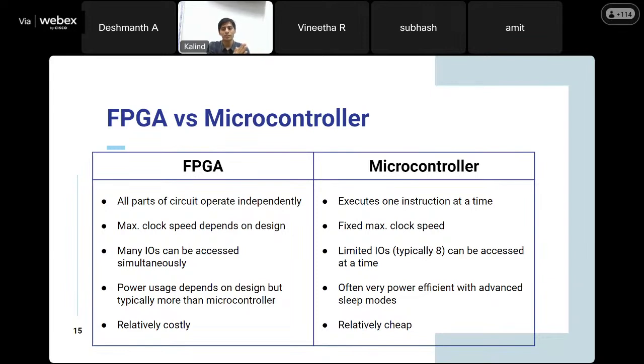And basically it means that when you are trying to implement lots and lots of boolean functions in those LUTs, you cannot have all the boolean functions implemented by a single configurable logic block. Why? Because LUTs have a maximum number of inputs, let's say 4 input or 5 input LUTs, right?